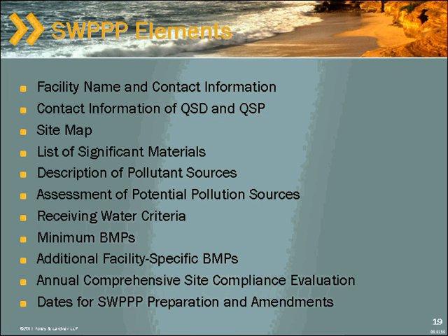The other side of that is 303(d) listed water bodies, where there's a pollutant that has exceeded a level, so it's an impaired water body. The debate is not resolved at this point as to exactly how to manage those 303(d) listed water bodies and how to deal with facilities that may have a pollutant that is contributing or potentially contributing to that listing. So we'll see when the permit comes out exactly how that is managed.